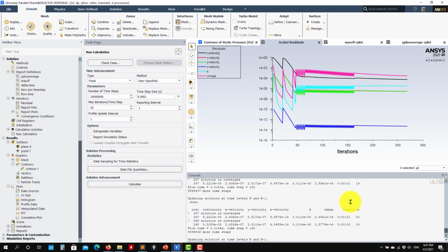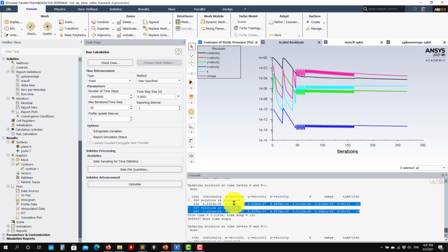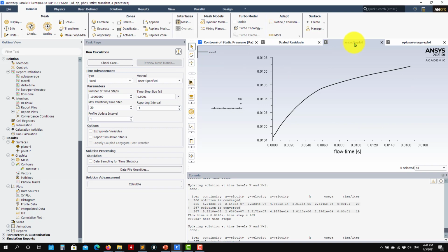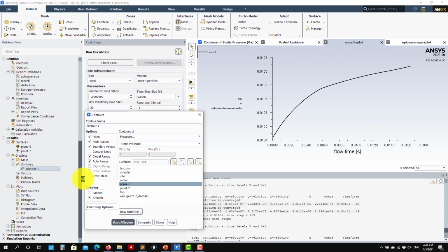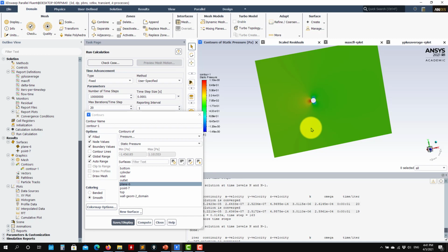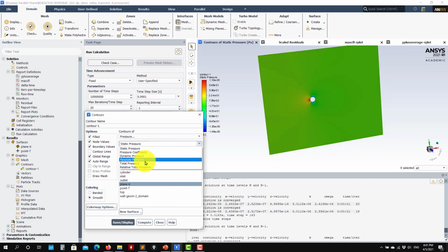What is happening is that each time step is converging basically in one iteration. This is what we want, a fast convergence, but we can still increase the time step. An advice here is that when you run, ideally you should converge in no more than 10 iterations. That is a good standard practice. You have this CFL number, and also we have a solution. We can post-process here. You can access all your fields and everything.